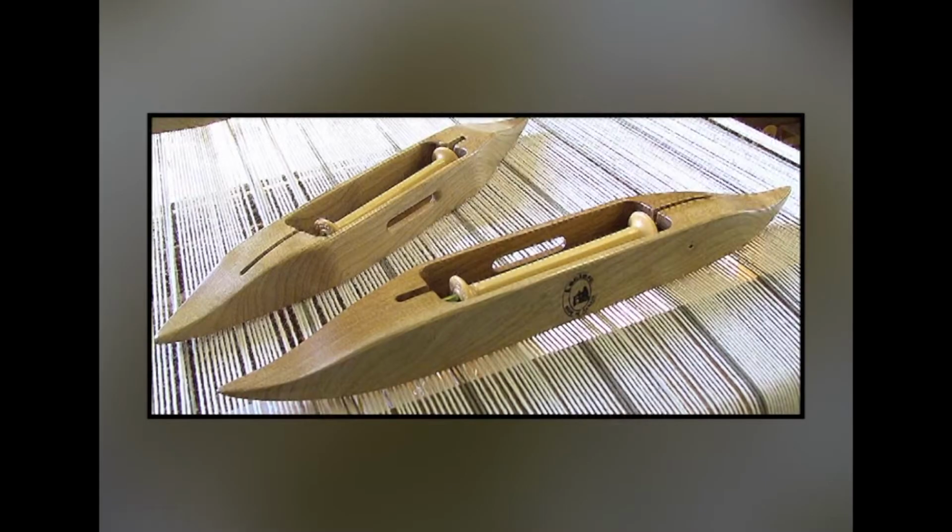Now in any of the conventional looms, the shuttle is the one that passes from one end of the warp yarn to the other end of the warp yarn. The weight of the shuttle is around 500 grams. Now this shuttle has to pass from left to right across the full width of the yarn. Because of this weight, the shuttle has to be hit from one side, or there has to be some power drive given to this shuttle so that it traverses from right to left and left to right.